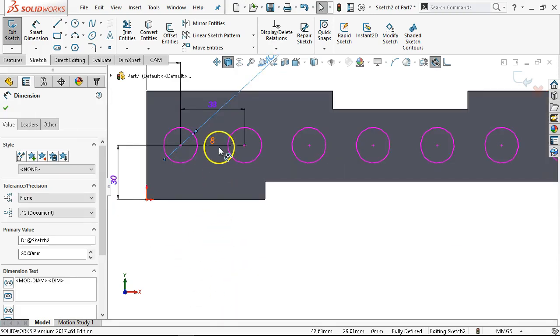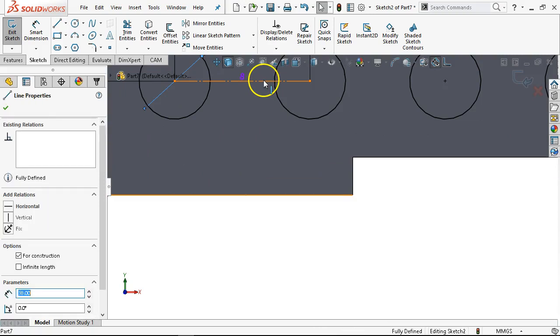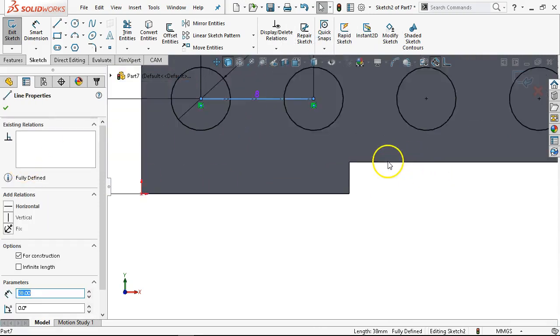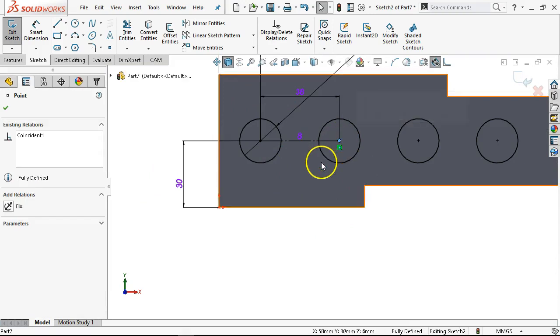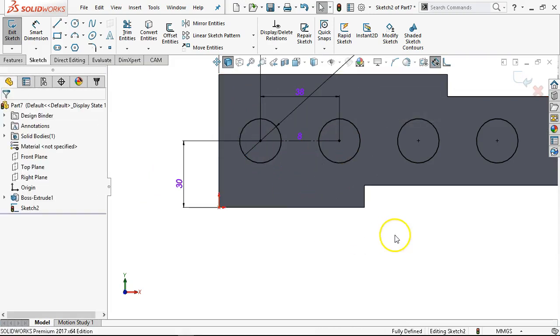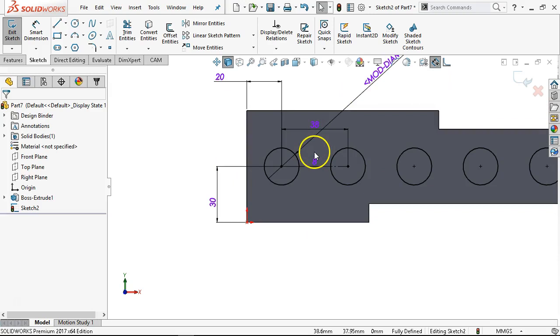So the difference is that this horizontal center line, it's still not getting going horizontal. So what is driving it? Coincident to the endpoint, coincident to the beginning. Dimension, maybe the vertical extension line.